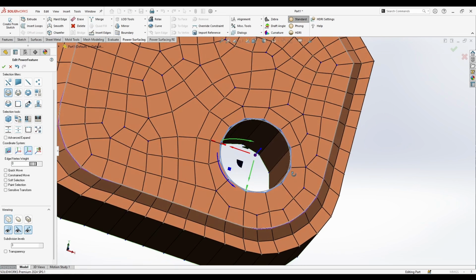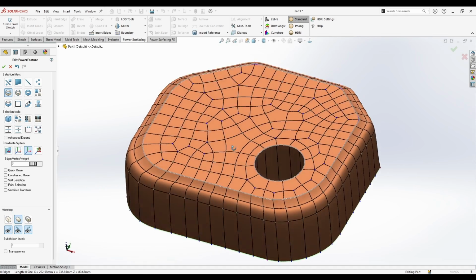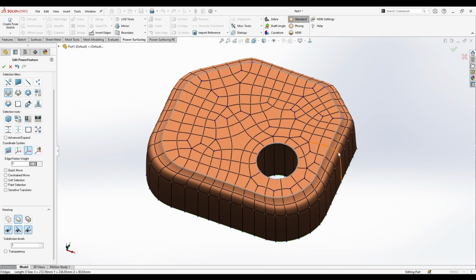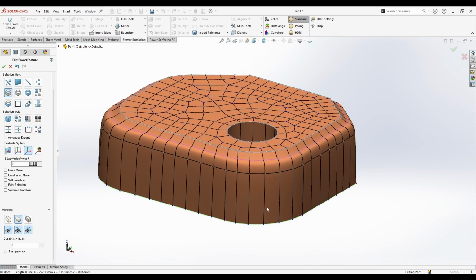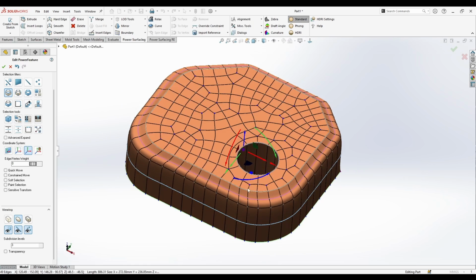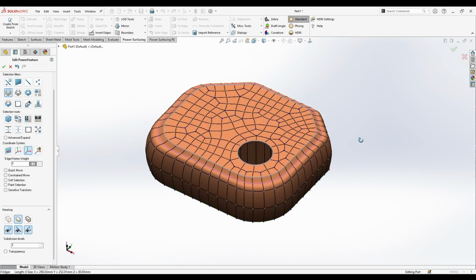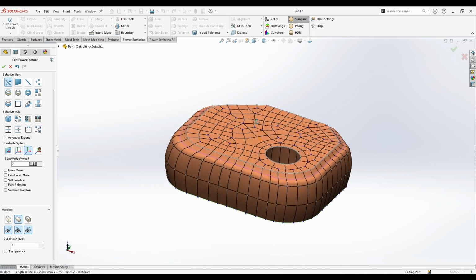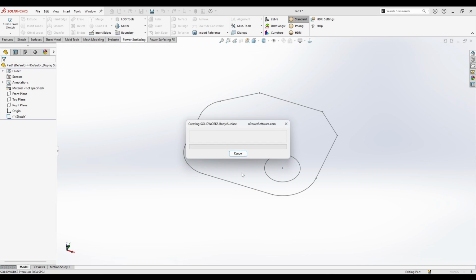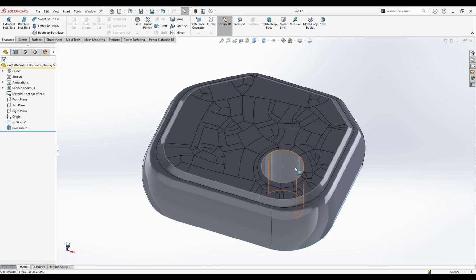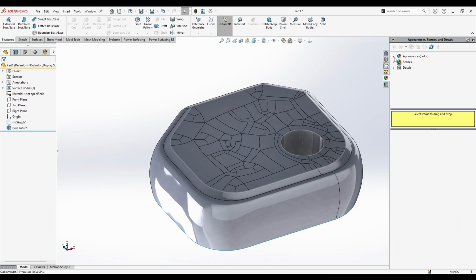So if I just created this hard crease here, go to the sub-D mode, you can see everything looks great. You can also crease this a little to give it a little sharp edge, and we can add an edge here, control how much I need here. So something like this. Okay, and if you just convert it, you can see your part looks great, and we just did a good job. It was create from sketch.